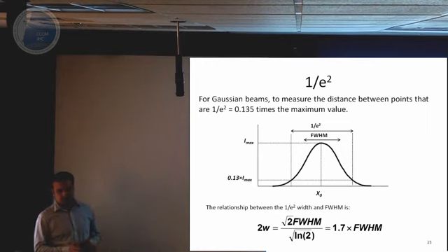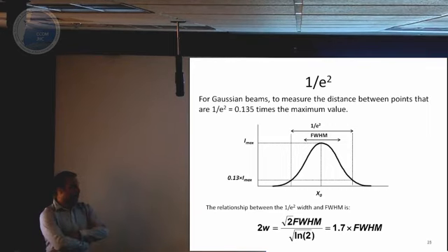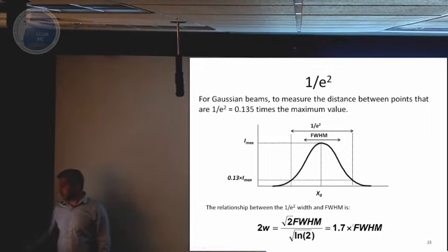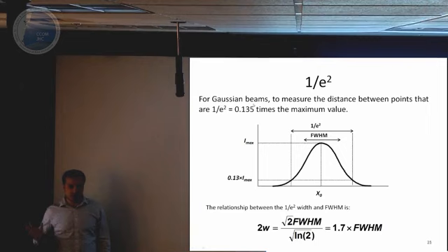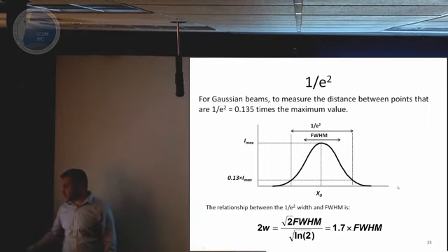What if our full width half-max interval is not enough for us to comment on the photoresistor outputs? So this is another method to set thresholds. It's related to full width half-max by a factor of 1.7, and it's also defined as 0.135 times the maximum value. As a result, the band widens.